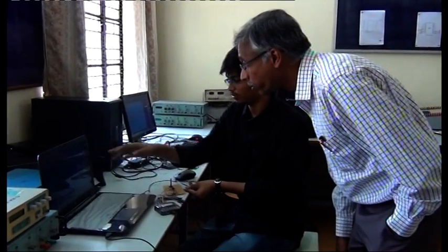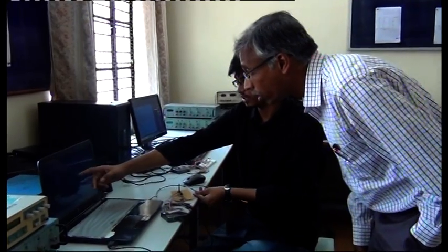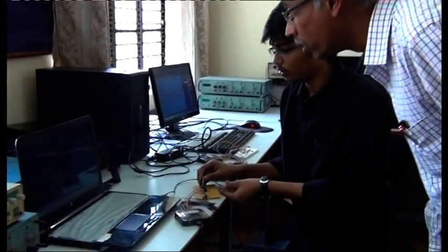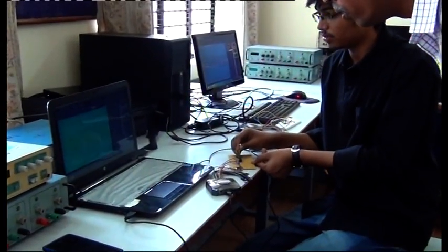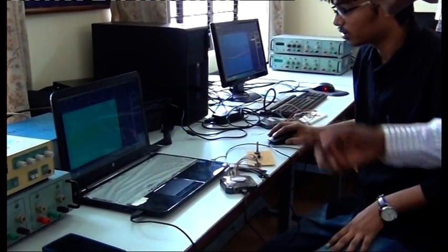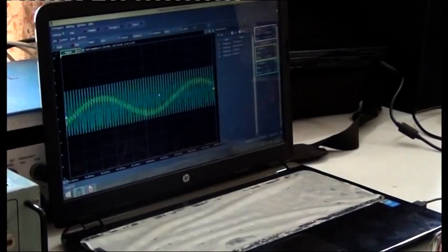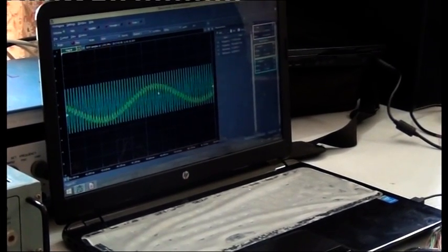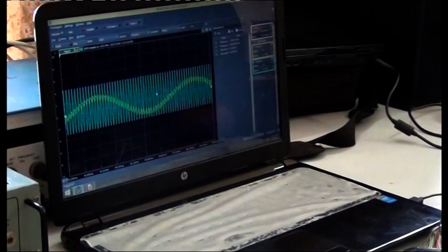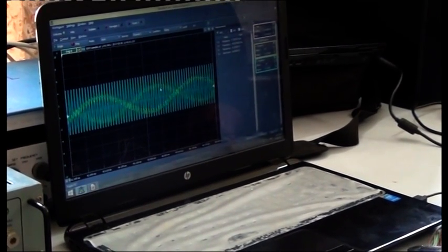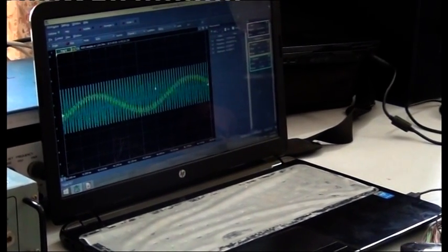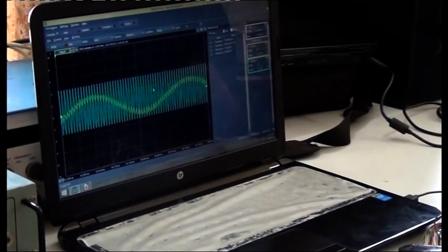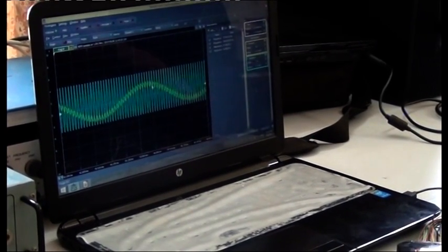System is acting as an amplifier, an inverting amplifier. Fine. Now, if you increase the gain, we are going to get the oscillation. Now it is oscillating. What is the frequency of the oscillator? Even though you applied a 100 Hz, 200 Hz input signal, the output signal is at 7.7 kHz. Now the amplifier is working like an oscillator. Now the closed loop poles are on the imaginary axis.